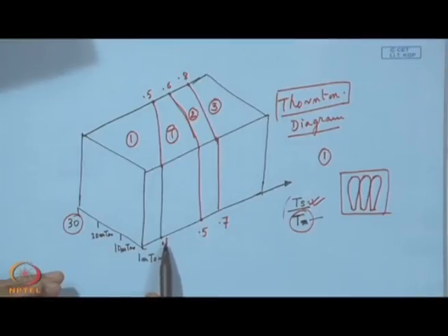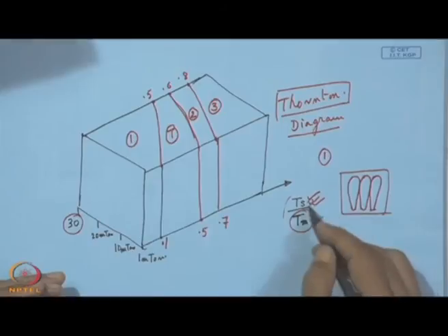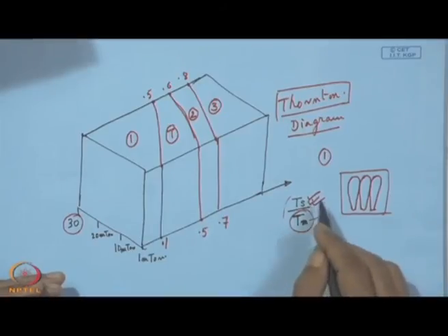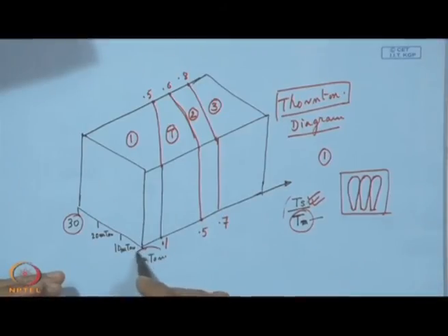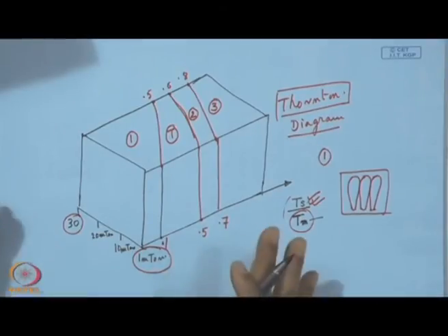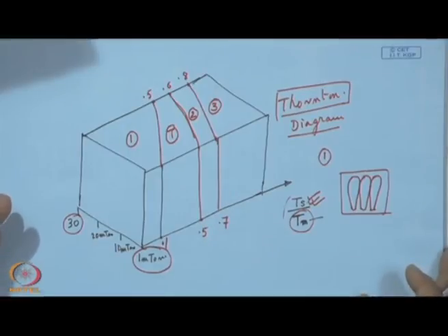In that case we can work with a low substrate temperature, provided we have the possibility to work with a low pressure, and that is possible by the assistance from the magnet, and that is called magnetically assisted sputtering or magnetron sputtering.